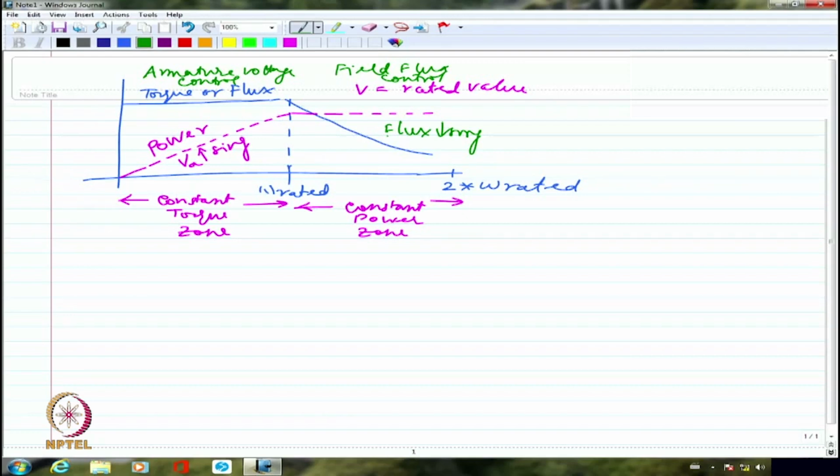But when I have decreased the main field flux to half the original value, from 0.5 to 0.25, then out of 0.25, the 0.05 or 0.1 will be a good fraction. So it will definitely take a heavy toll on the main field flux when I compare it with the armature reaction flux itself.